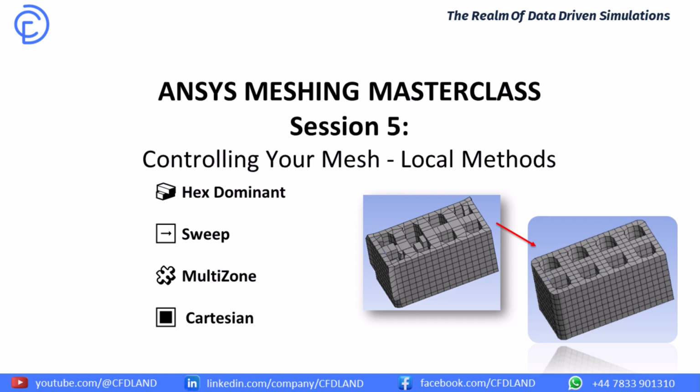First, you will understand what each of these four powerful methods on your screen does: hex dominant, sweep, multi-zone, and Cartesian. But much more importantly, you will learn the secret that separates a beginner from an expert. You will learn how to choose the correct method. By the end of this session, you will have a clear, simple guide. When you see a new geometry, you will know exactly which tool to use to get the best possible mesh.